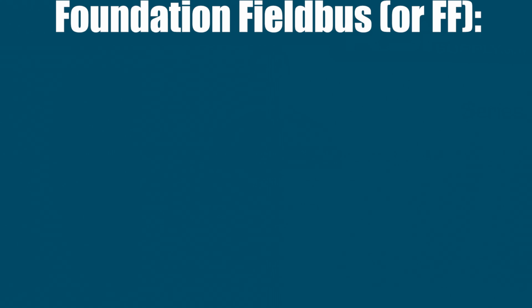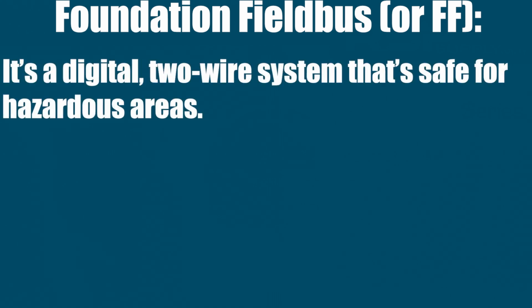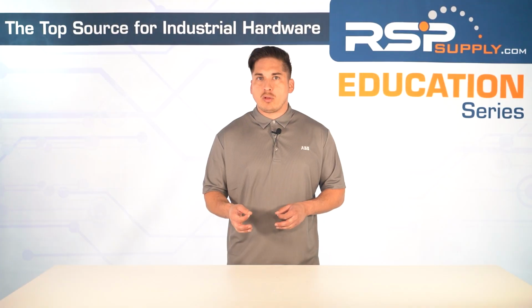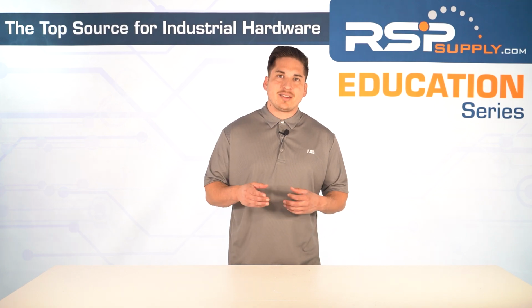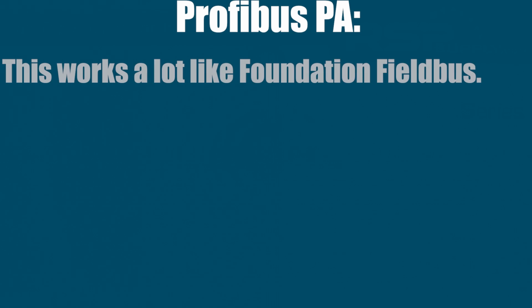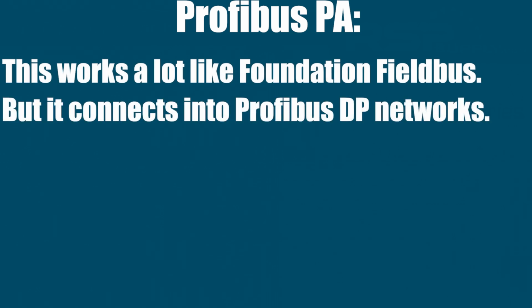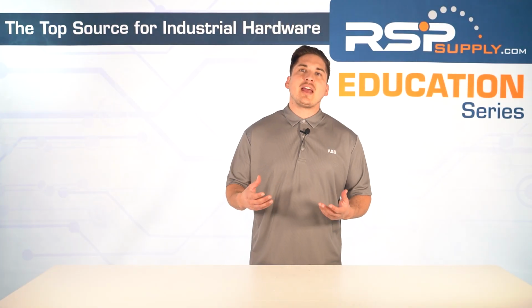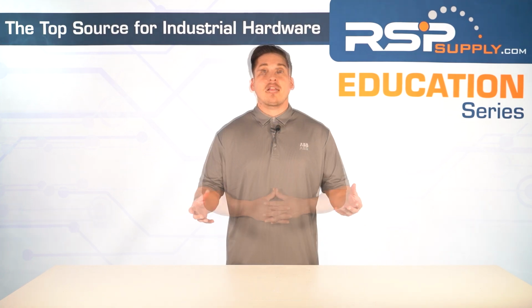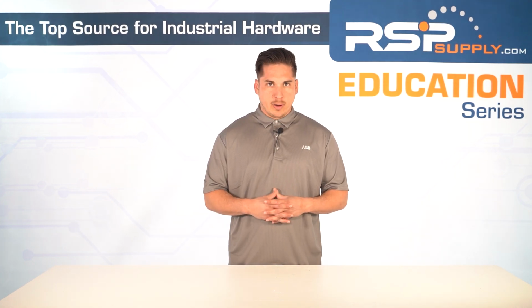Foundation Fieldbus, or FF. It's a digital two-wire system that's safe for hazardous areas. It supports something called function blocks. That means your control logic can run inside the field devices themselves, not just in the PLC. Profibus PA works a lot like Foundation Fieldbus, but it connects into Profibus DP networks. You'll see Profibus PA more often in European industrial plants.